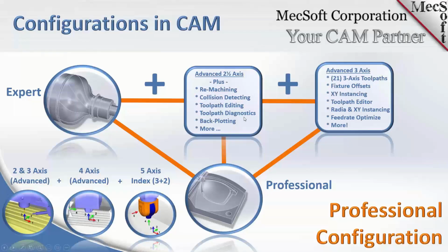One of those is toolpath diagnostics. If you're having difficulty with your toolpath, you want to get more information about it, you can do that in the Professional. And also you can backplot your G-code, okay, and many more features.